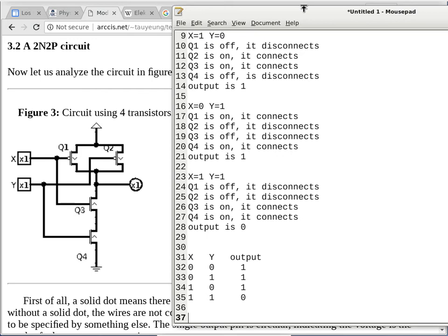It also looks like an AND, because as long as I have at least one input being a 0, the output is one particular state. The only time the output is the other state is when both inputs are 1s. That looks like an AND, except it's opposite to an AND, a conjunction. We cannot do this with a single operator, but we can do this with 2 C++ operators. We need a negation after a conjunction, after an AND. Okay? So I will let you guys work this out.